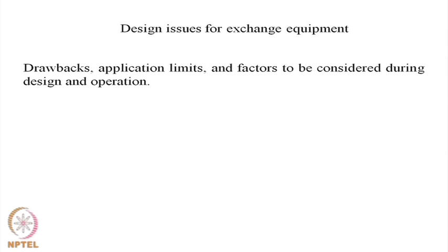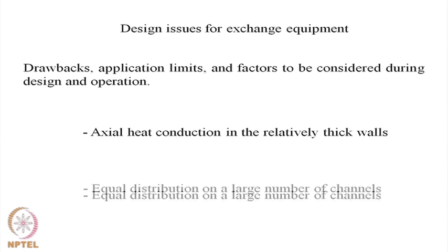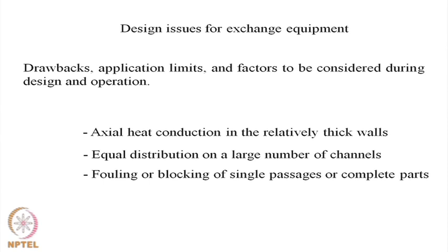And if we think about the design issues for exchange equipment, when we consider heat transfer, it is the axial heat conduction in the relatively thick walls which reduces the delta T available. And if it reduces the delta T, then our process efficiency gets hampered. How do we distribute the fluid equally in all channels?